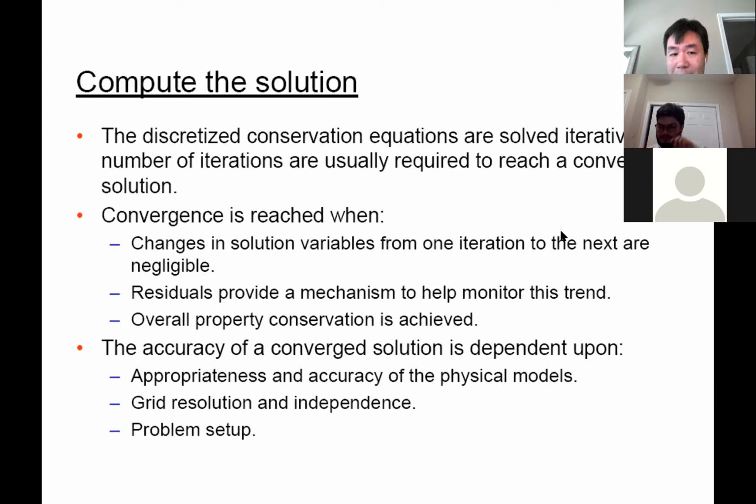That result represents the result at that time. So it will propagate 60 times. If you put the time step as 1 second, then it will go 3,600 times for an hour period. So it will calculate at any moment what the flow looks like. So these are the two types of simulation you are going to do. You are going to do steady state and unsteady simulations in the two projects we are going to do.